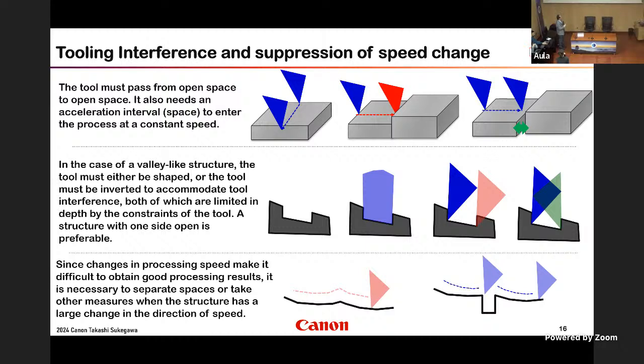This is very important. Traditionally, 10 years ago or something, very old, our image slicer was made with the tool itself, a very small tool, just machining in one direction, very easy. But recently, the end customer requires not a flat surface. So we say single point machining, but we have to make that shape.